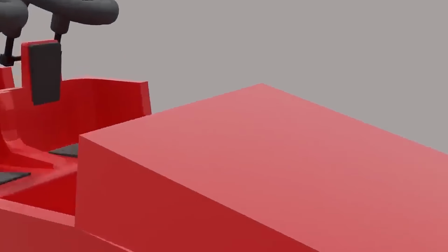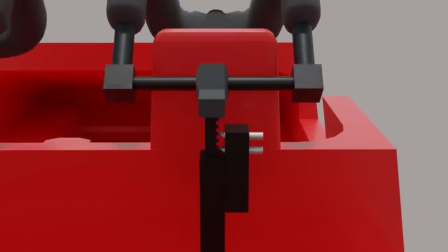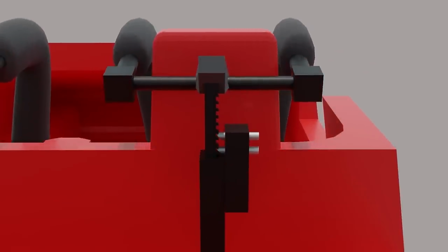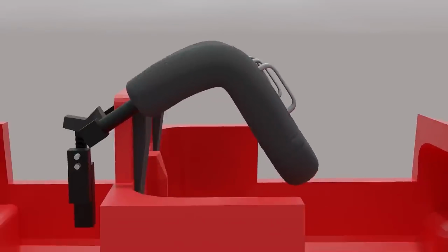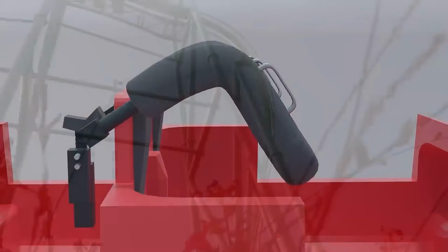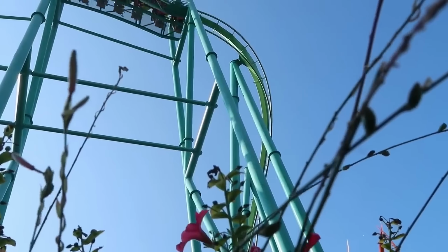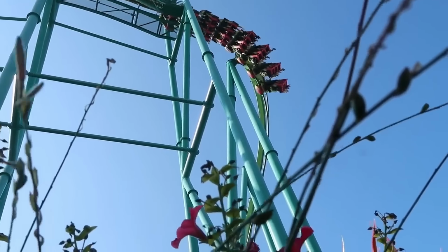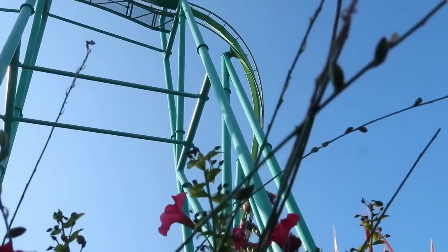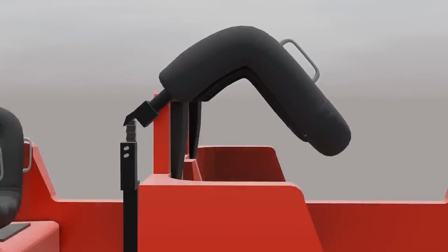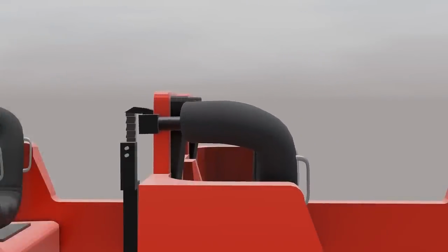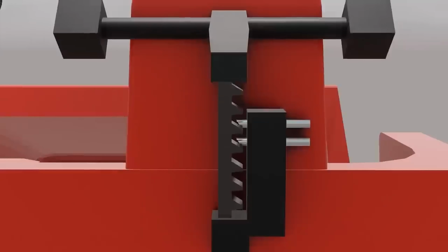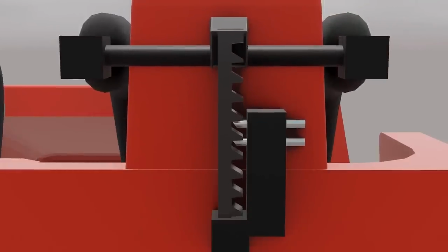The next type of restraint was designed to replace the single position latching restraint, the multi-position ratcheting restraint. This design works off the simple principle of a ratchet, a mechanical device that can move freely in one direction but is unable to move in the opposite direction. The simplest of these designs use a toothed rod with locking pins, usually at least two for redundancy. These pins slide into the rod, preventing it from moving down but allowing it to move up.